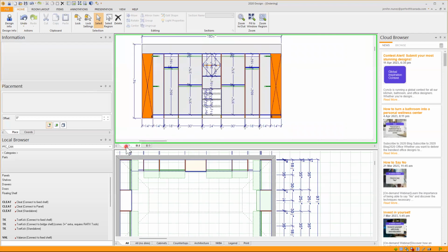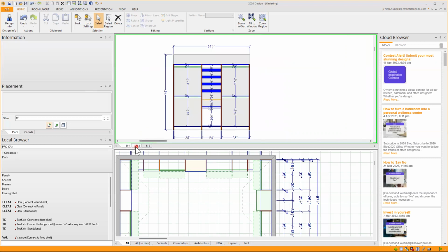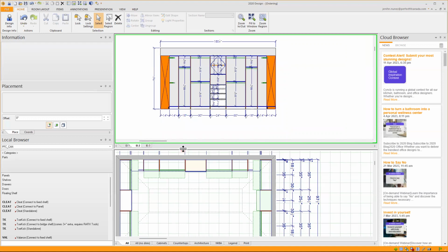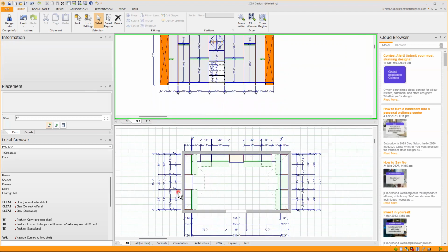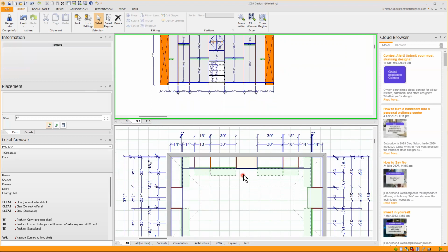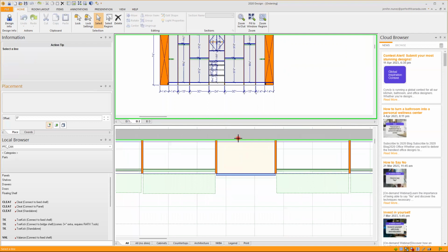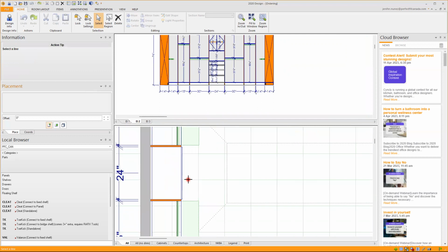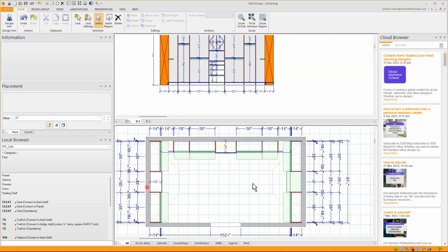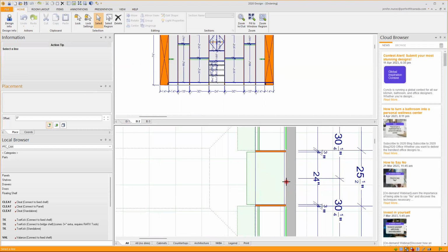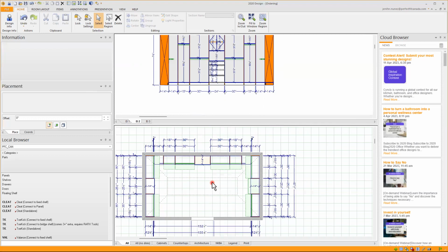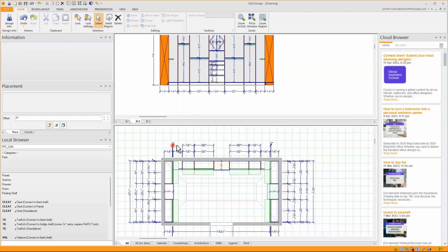So I have all my dimensions, my line to line dimensions, in my elevation. And if I go to my plan view here, a lot of dimensions populate there. We always add one more in the plan view to show how deep the models are, especially when you have different depths, so they know there's a section of 24 inches if you have one, and so on.